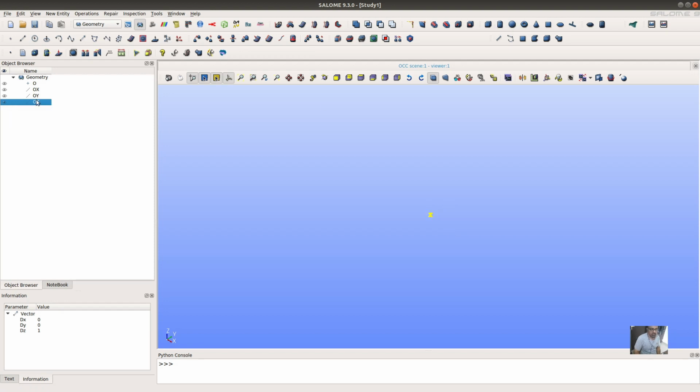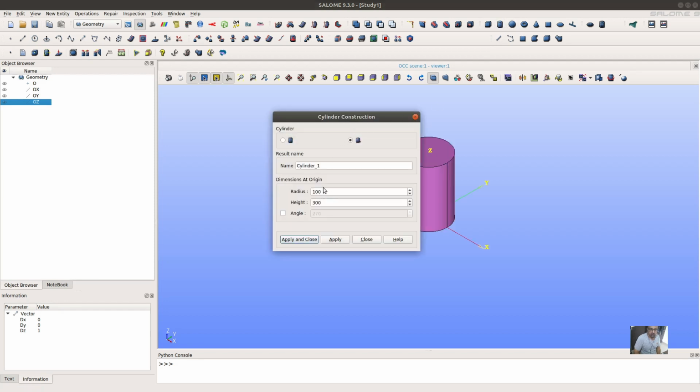First we need to select the axis, then select the object like pipe. We need the radius and height of the pipe. Height means the length of the pipe here. The axis is the z axis. We have considered 10 mm radius and 500 mm height of the pipe.